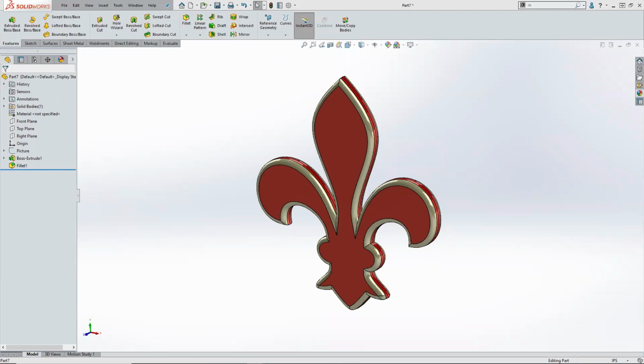Was there another question? No, this is Ray. I was just talking about a fit spline. That works well. I was running it the other day. I used a fit spline to create a surface without tangency lines, so I could actually put a cam follower in and have a tangency mate where I could have some motion.